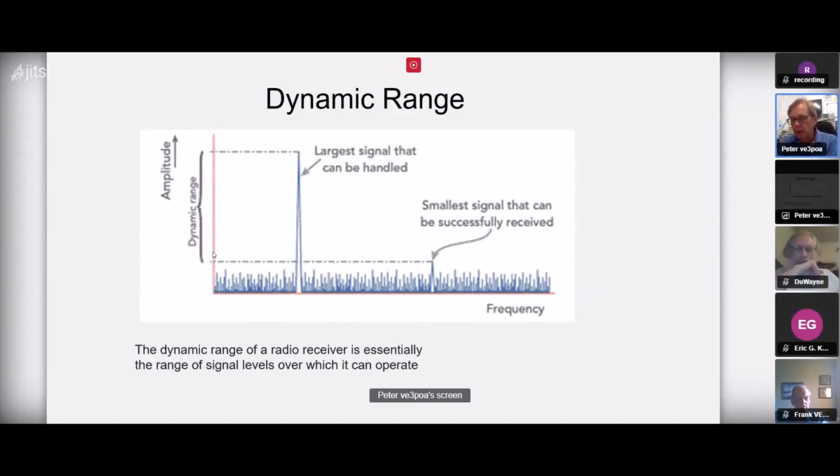Input impedance matching is critical for this. Components using an active device should be selected for the noise performance. Front-end output capability: the front-end amplifier should have a relatively high output capability to ensure it does not overload. The RF design must provide sufficient output capability so as not to generate high levels of noise. Again, don't set them up max.